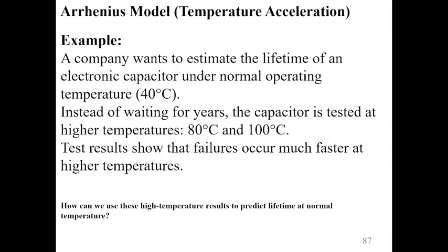Test results show that failures occur much faster at higher temperatures. So how can we use these high temperature results to predict lifetime at a normal temperature? This is the question. We answer it by using the Arrhenius model.